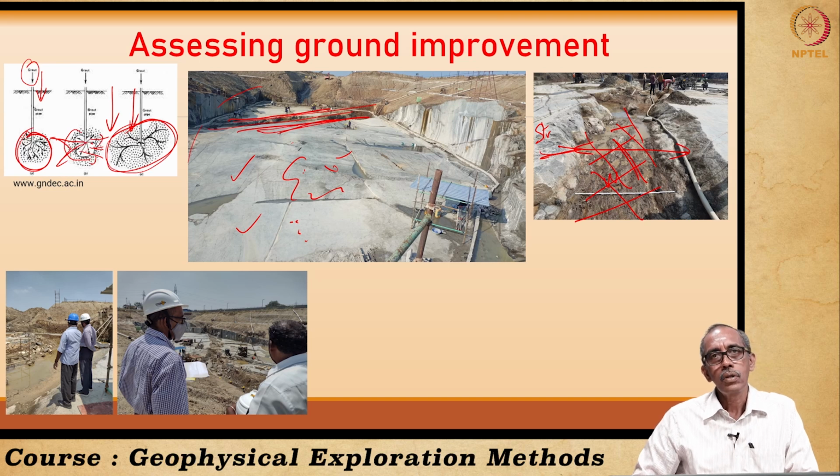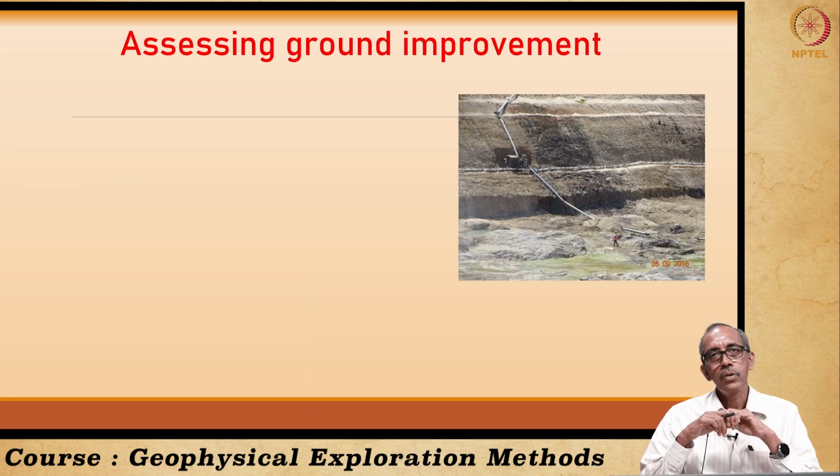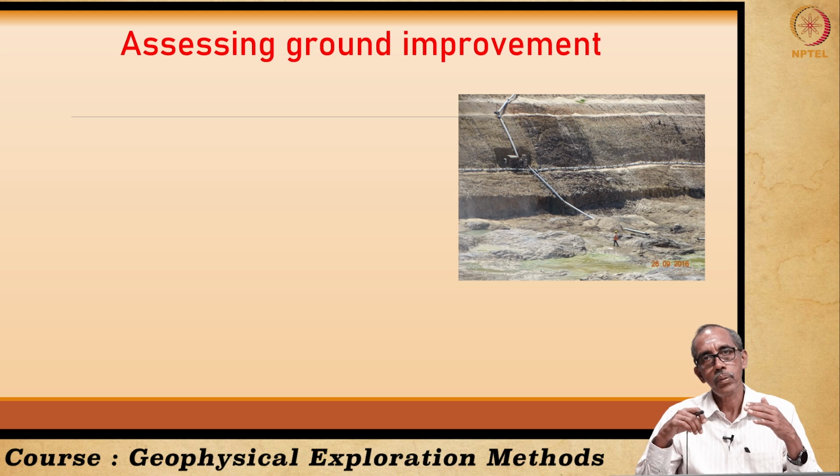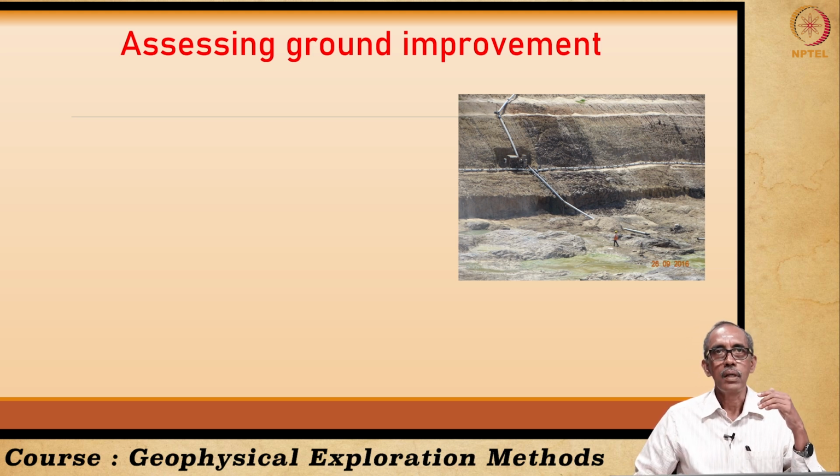And we can also use seismic refraction survey to understand how effectively we have carried out the ground improvement. How can we do that? We can do that by repeating the seismic refraction survey. That means before ground improvement, what was the shear wave velocity? After we carry out ground improvement, how has the velocity improved? That is what we are going to do.